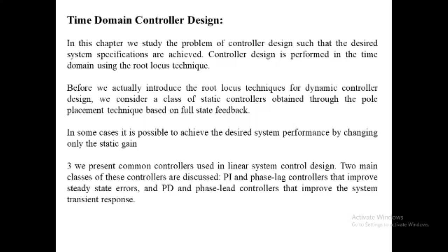And the third one is that controller design using the root locus method is simpler than the corresponding one based on the Bode diagram. Next, this root locus controller design technique is equally applicable to both minimum and non-minimum phase systems, whereas the corresponding technique based on the Bode diagram is very difficult to use for non-minimum phase systems.